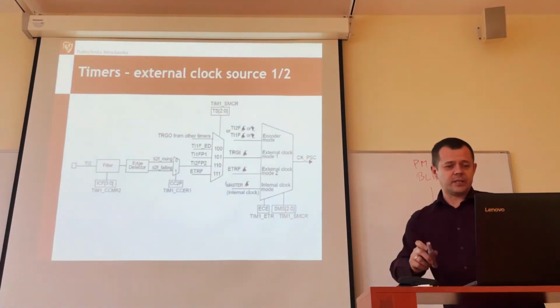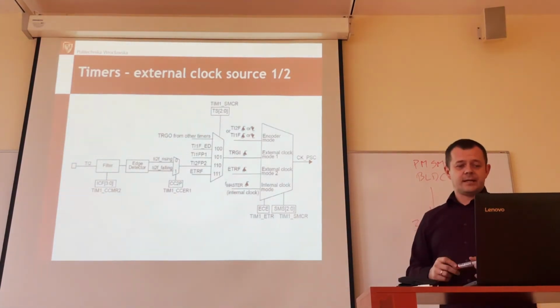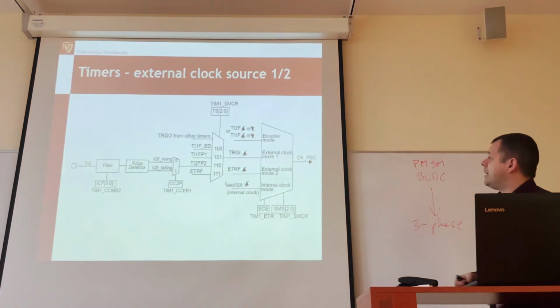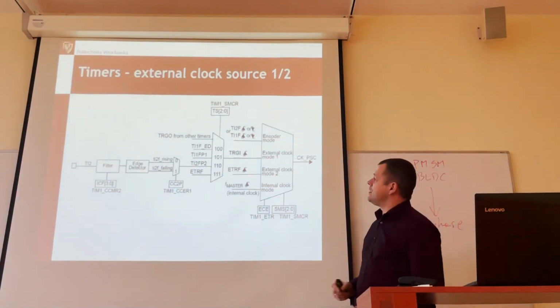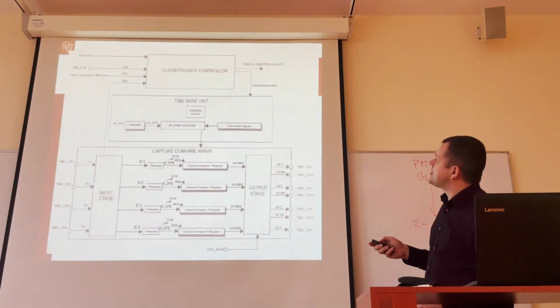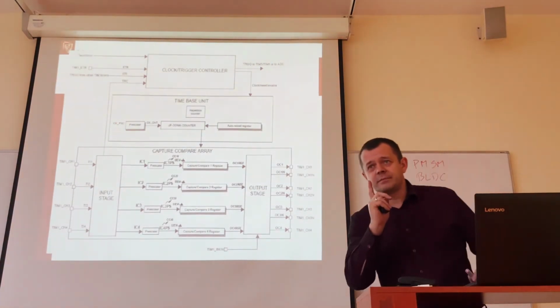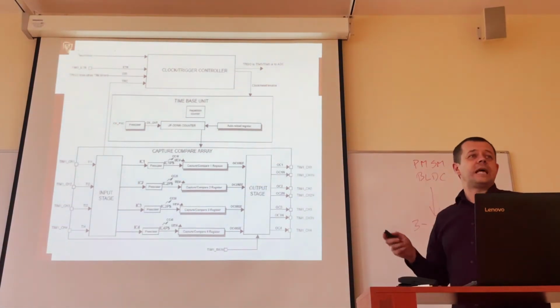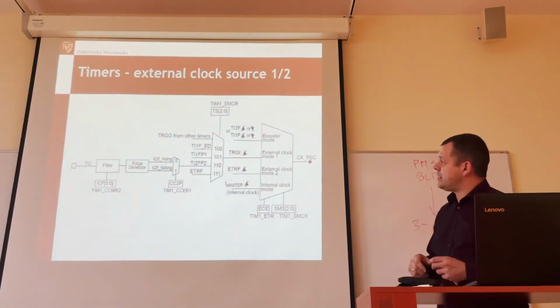Yeah, in microcontrollers, and that's also the case here in this microcontroller, we can quite often choose the source of the clock count going to the prescaler. So this is again CK/PSK. This is the clock. Take a look here. I mentioned that it's sometimes a guess game. What is connected and what's the frequency? Something that we have to be very careful about.